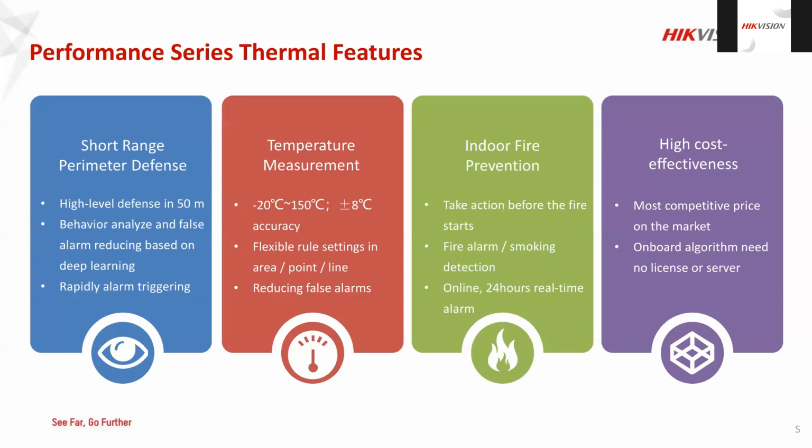So when there's a fire, the camera can still detect it, but the effects of that fire will not affect the lens. If the environment temperature is high, we definitely have to check our data sheet and make sure the product can tolerate that environment temperature. You should not point the camera directly into the fire or get in contact with the fire. That will definitely destroy the lens and the camera.